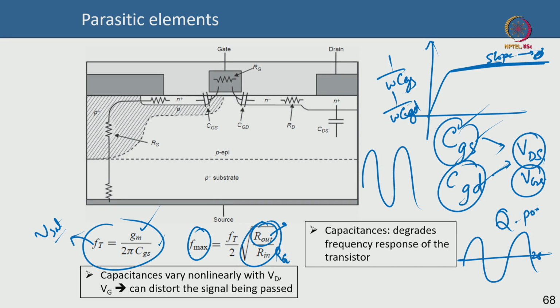People do a large signal nonlinear model of this device. For that, people use pulsed IV in conjunction with load pull data. Load pull means that you are going to measure the output power, you tune the load, you find out the different impedances. And from pulsed IV, the behavior of the device under the pulse condition. People use transient and thermal effects also. They do large signal modeling, and that is very crucial in designing the amplifier, output matching and everything. So, this nonlinear dependence of capacitance is generally a worry, but that is something unavoidable.